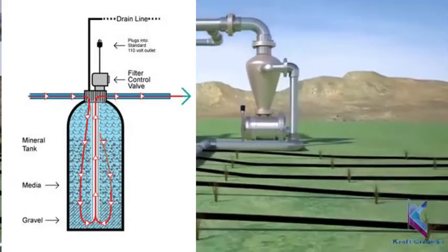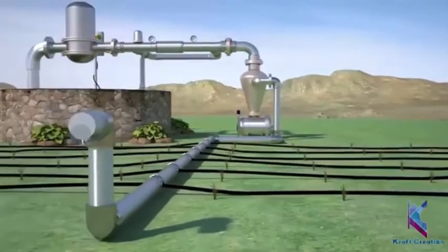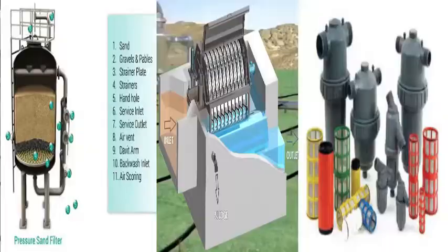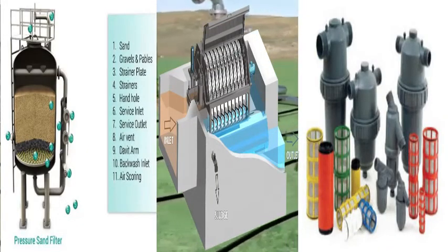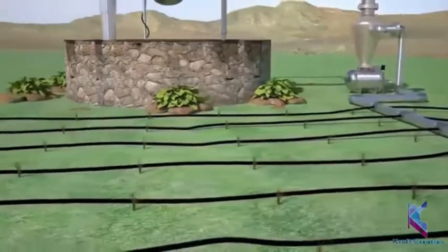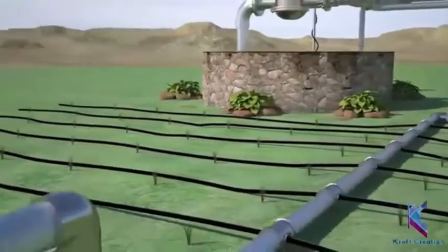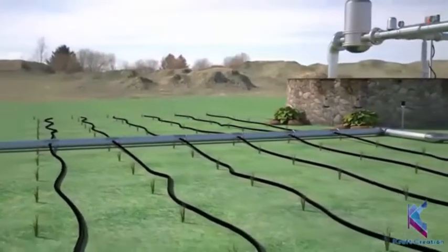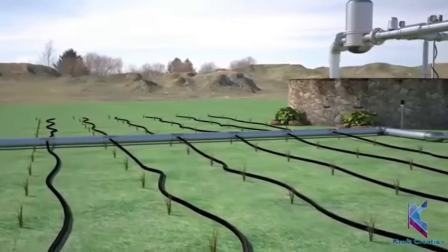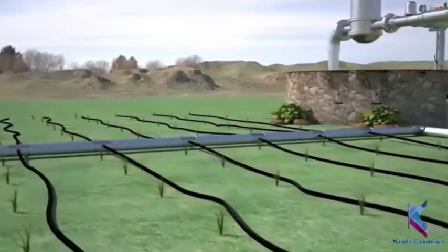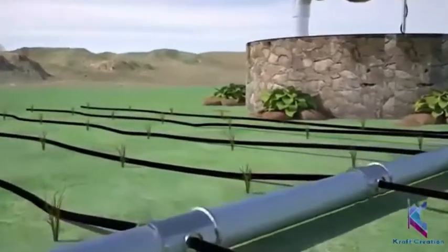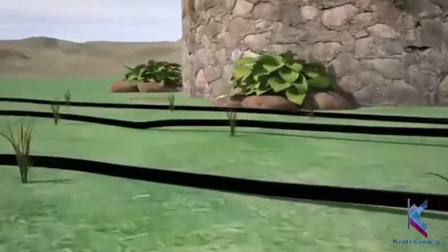Some systems use demand dosing to the drip field with a manual filter and field flushing, but this is not recommended. The filtering device can be a sand filter, disc filter, or screen filter. Its main purpose is to remove large particles from the wastewater so they do not plug the drip emitters. Depending on the system design, the filter may have an automatic backwash that can be activated by the pressure differential before and after the filter or on a predetermined frequency.